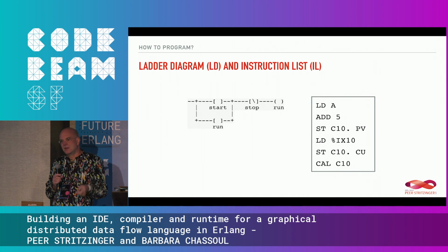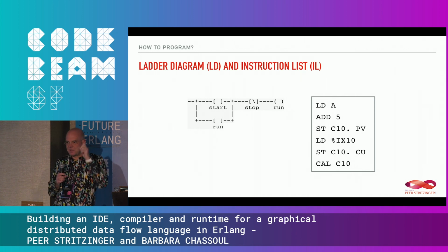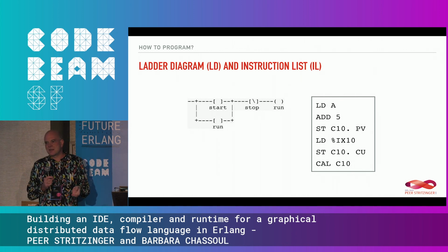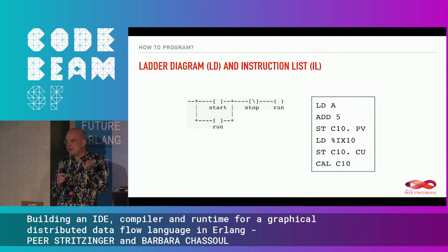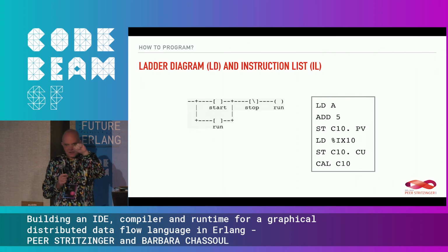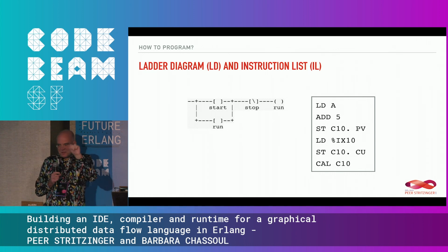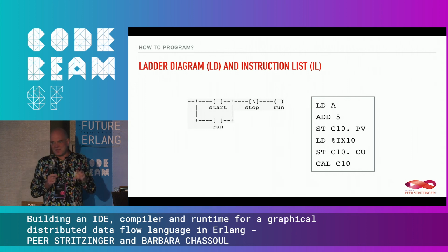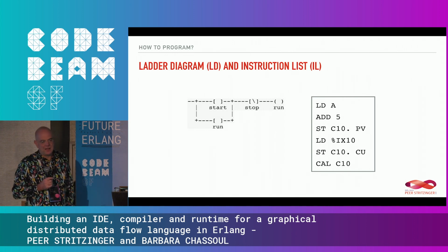You had coils, and the coils operated switches, and there were a few specialized relays which had a delay. When you put it on, there's a capacitor charging, and then the switch goes on after a while. And you can have a little dial on the front to set the delay. So there are all these relays.